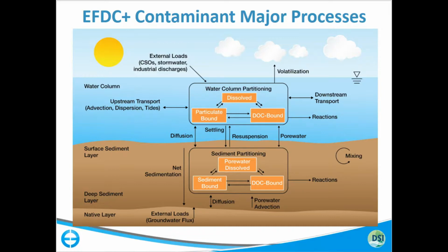The mixing component, there's a bioturbation / mechanical disturbance depth and a diffusion rate that you can specify in EFDC, and it'll mix not just the water, it actually mixes the particles, and will smear out any kind of like a front or something in the near surface.